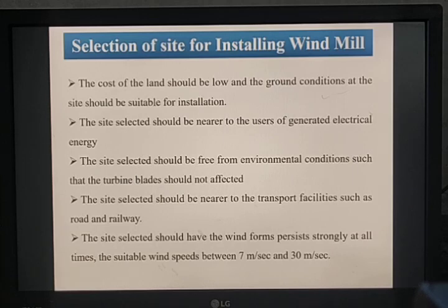And significant tourism infrastructure places: it should be attractive for tourist places. For those particular places we can erect or construct the windmill. And land use is primarily for grazing and cropping. These are the various primary site selection criteria for a windmill. The first one is that it should be constructed near roadways, and another one is that we want to measure the annual average wind speed. Next, the land should exclude conservation land, it should be constructed near the national power grid, and it should be attractive for tourism infrastructure places. These are the various criteria for selection of a site for a windmill.